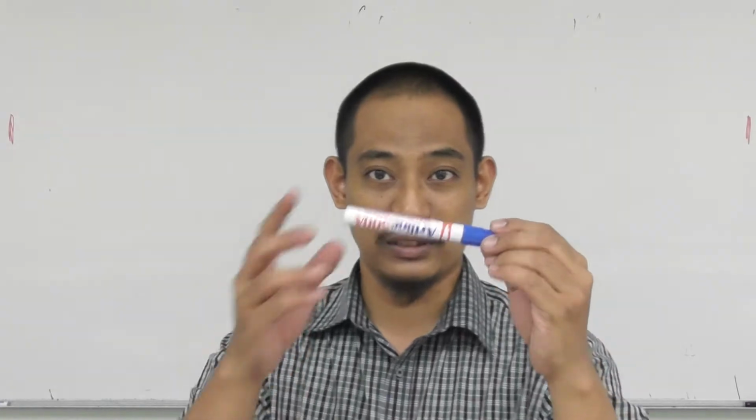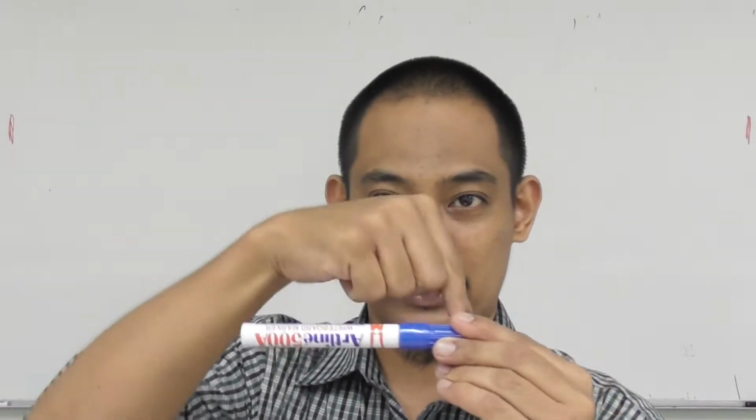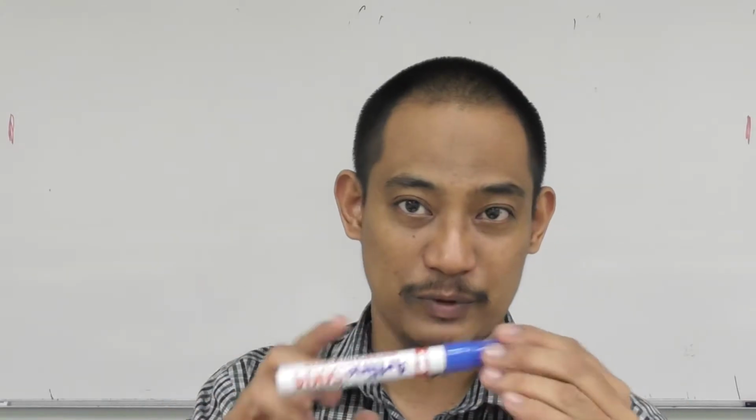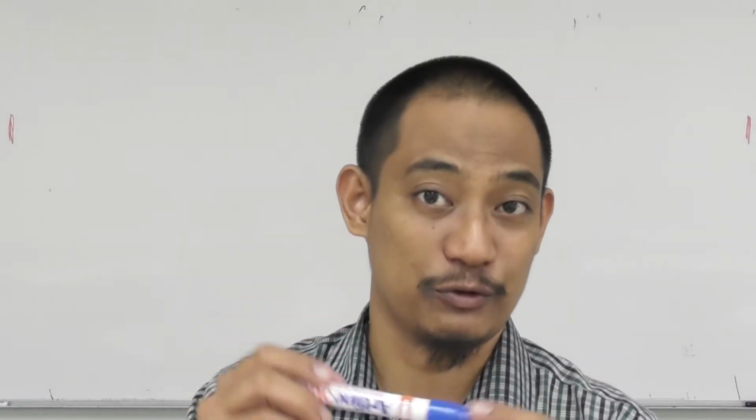So when we deal with equilibrium of rigid body, this is an example of rigid body. It is rigid. So if you have a force here, here, etc., the distance between all the forces does have an effect in terms of the tendency for rotation. Hence, whatever we have covered in chapter 4 will be important in chapter 5, and what we have covered in chapter 2 also will be important, because normally, especially in a 3D body, we have to know how to deal with getting every force into Cartesian vector form, because that's how it is easier to calculate the moment, etc. Right?